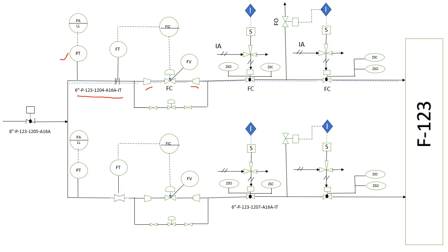FC means fail close. Also there is a bypass around the valve, and then another on-off valve which is fail closed, and there are feedback limit switches ZSO and ZSC, and how it is operating. It is operating through an interlock number; you can find everything in this detail.